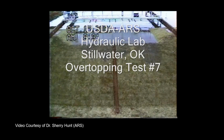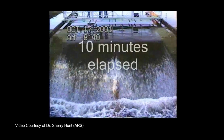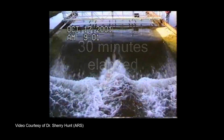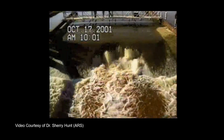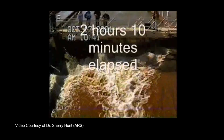This is a great video from Dr. Sherry Hunt and the Agricultural Research Service. They looked at just removing a strip of grass to replicate a tire track, and they did a series of studies of flow over the grass lining with that one defect to see how that affected the rate of erosion. As you can see in this time-lapse photography, it's only where that bare earth or tire track was simulated that initiated the failure. Had that feature not been there, this spillway would have performed satisfactorily and would not have breached.